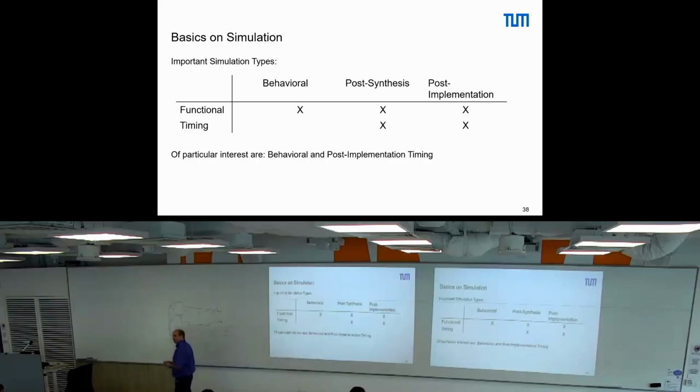But if you want to really do it in a circuit simulation, then you will end up with these ranges, these margins where each delay is inside. So both are critical paths, one is the longer one. I've drawn both of them because the question now is: we have a longest path, we have a shortest path, we have a clock path, maximum, minimum. What do we have to compare?